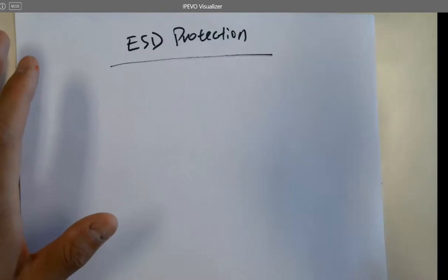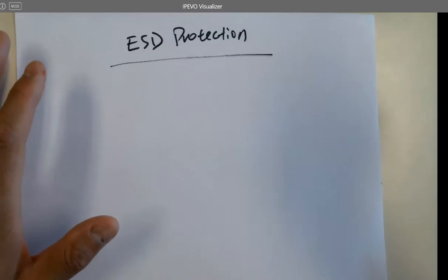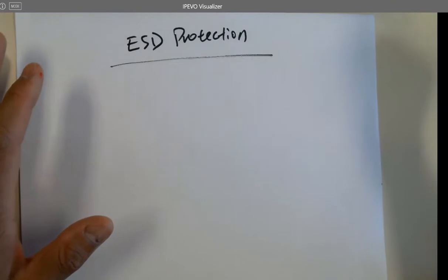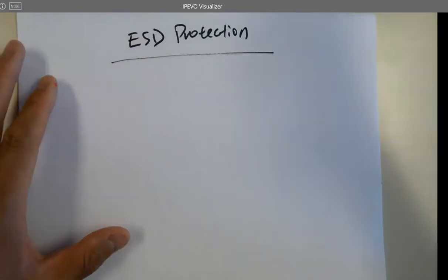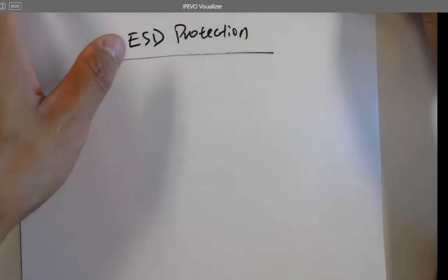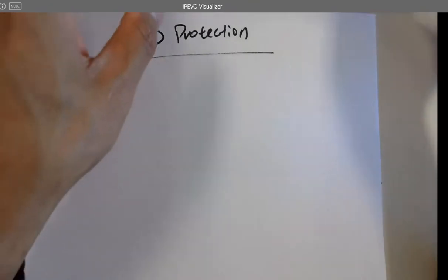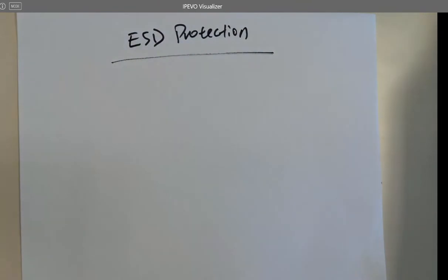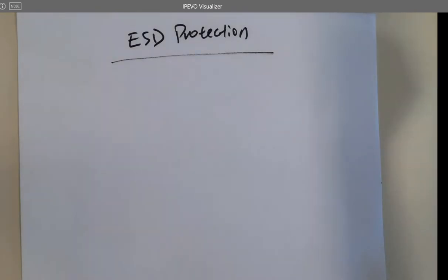We can ground it, but sometimes it's just so time consuming. In practice, in my lab, we never did that. Probably it's damaging 1 out of 100 chips. If it's damaging like 10 out of 100, it's pretty significant, so we probably would do it.